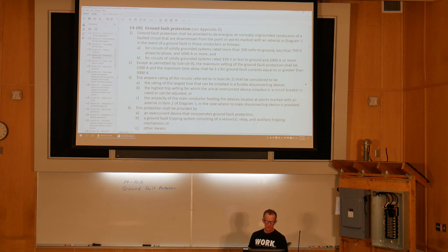B, for circuits of solidly grounded systems rated 150 volts or less to ground and 2,000 amps or more. So 120/208, 120/240, etc. Subrule 2. Except as permitted by Subrule 8, the maximum setting of a ground fault protection shall be 1200 amps and the maximum time delay shall be 1 second for ground fault currents equal to or greater than 3000 amps.